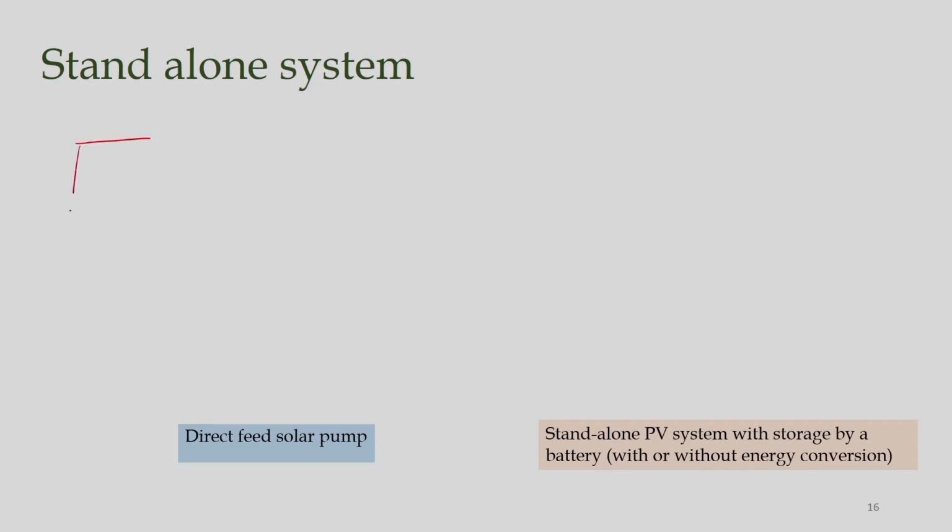We need to have some kind of solar modules. Okay. So, these are solar modules. These modules are maintained at a certain angle based on the location, and solar radiation is falling on this module, okay, and current is generated, and then we need to convert this DC current to AC current. Okay. So, by using this inverter,